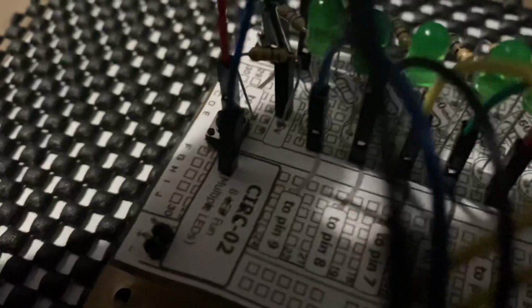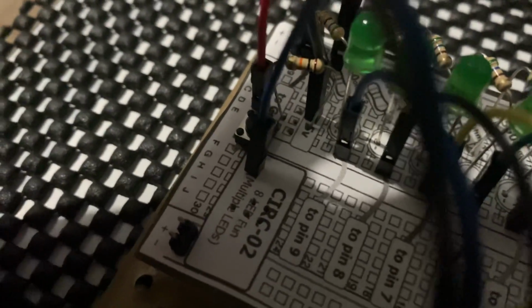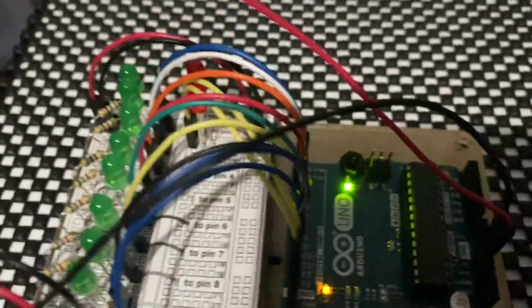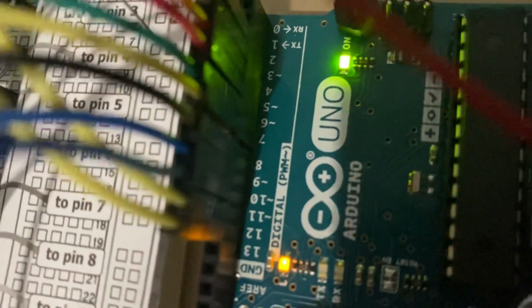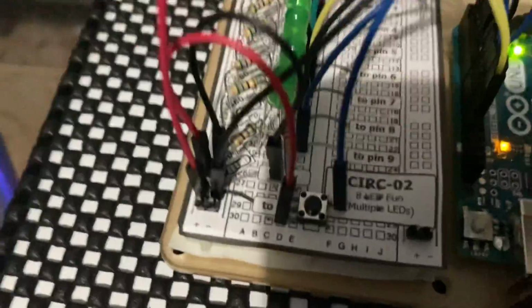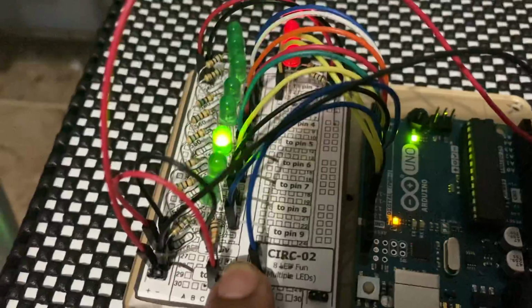It's kind of hard to see. It's a little compact, but right through there you can see one part of the button is connected to the ground via the 10K ohm resistor. And then lastly, we have on the other side a blue wire connecting it over to digital pin number 10. And that is it for the button. That's how the button operates on power and how it connects to the pins.